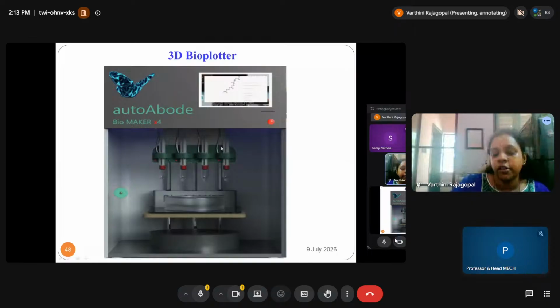I'll show you. There are 4 types of release. Immediate release: as soon as you take the tablet, immediately the drug will be released. For that you would have a very porous-like structure. When taken, it will immediately dissolve in your gastric acid and release the drug. For sustained, you can have a higher infill density. Throughout the day, slowly it will start to digest, and at the end of the day, the dosage will be spiked. Chronic release: with time, the profile will vary. Here the outer portion will be denser and the inside portion will be porous. Like that you can design your tablets patient specific.